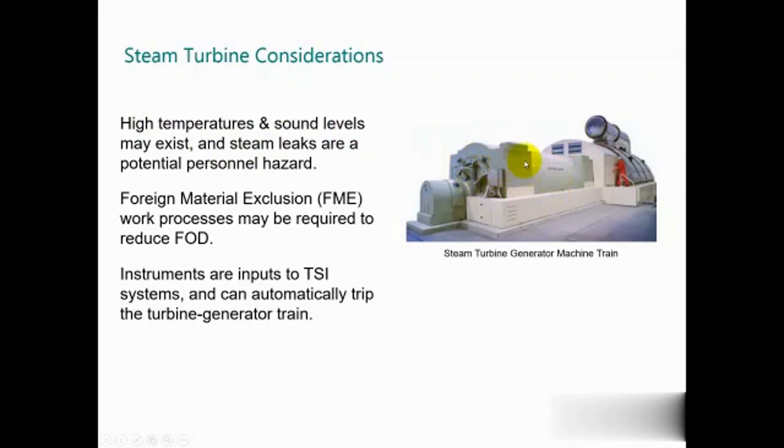And the steam, that means there is steam in the surroundings. You need to check for steam leaks. If you observe that your vision is blurry, please don't pass. Normally it is overheated steam. It is invisible, but the temperature is over 100 degrees Celsius or 212 degrees Fahrenheit.